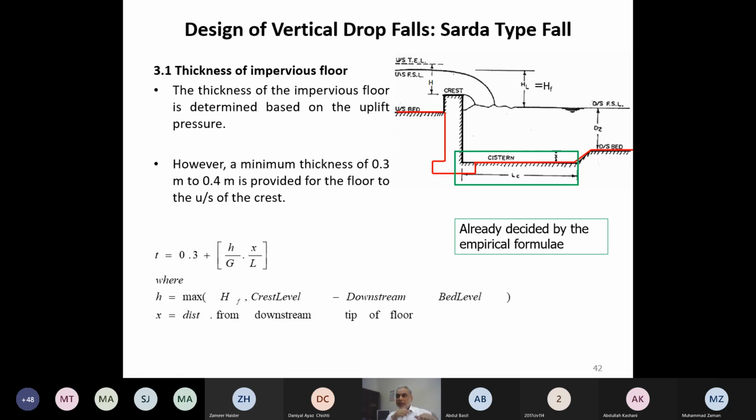While in the case of the RCC slab, which takes care of flexure also, the piers will be supporting the slab, and then we need to provide some flexural steel over there also. Some of the barrages have been designed using that concept. In that case, more steel will be required, but less slab thickness. So these two concepts have been utilized in the case of barrages.